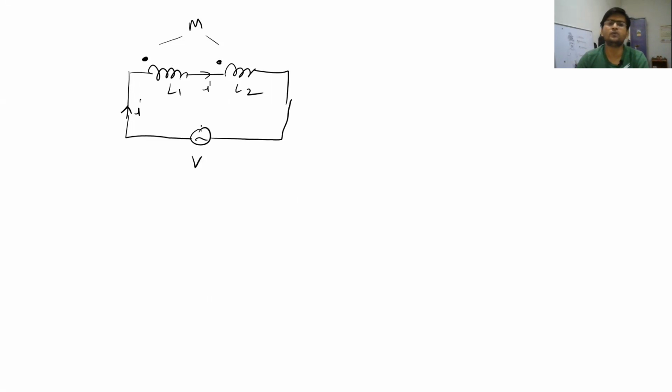If you want to write a KVL equation for this circuit, we can write Vt is equal to L1 di upon dt plus M mutual inductance times.